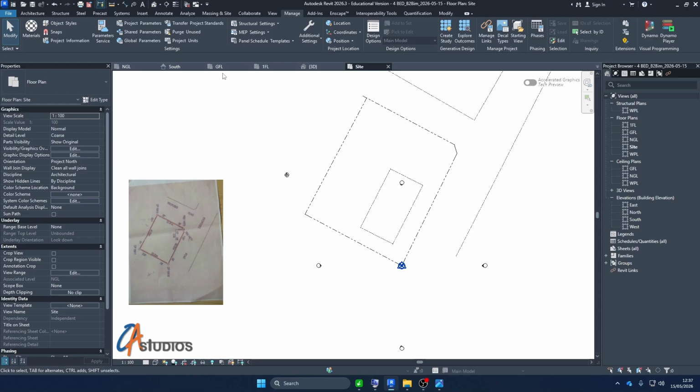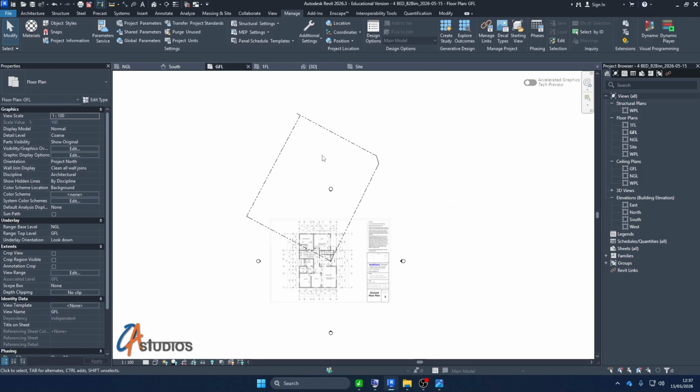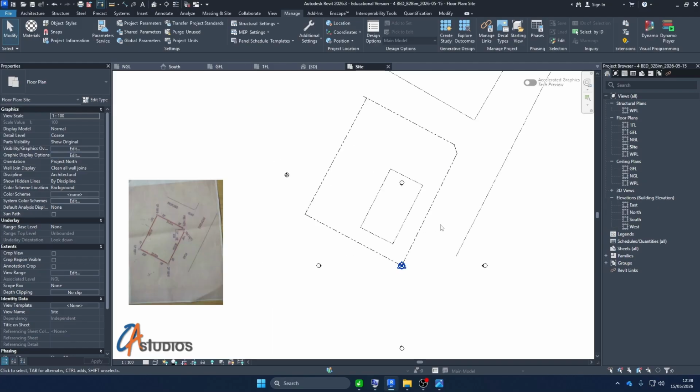So meaning if this ground floor is facing this way, the north arrow on this ground floor, because it's straight here, automatically when this is straight, the north arrow has to face another direction, on this particular view. So I have the opportunity to have a true north facing up, and a project north in another direction, so that my views correspond to what I want to have.